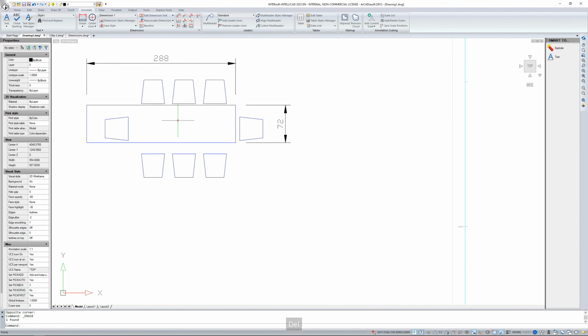But sometimes you prefer that dimension not to be pinned. In this case, if it is to be detached from the element, then I enter the dim disassociate variable. That's dim disassociate. Please have a look at this icon that looks like an unlocked one, so an open padlock, and a dimension, so unlocking this dimension.